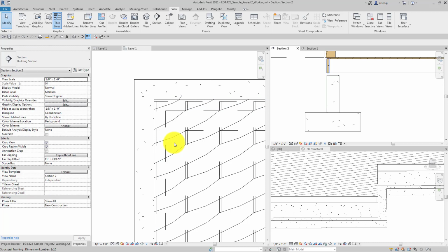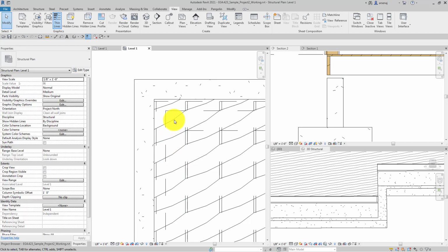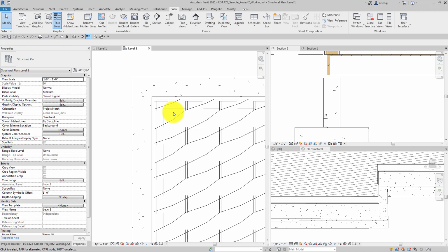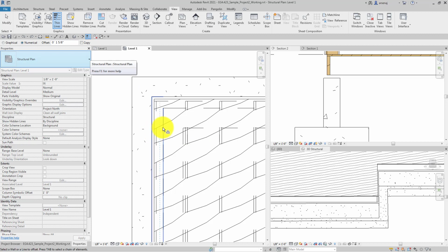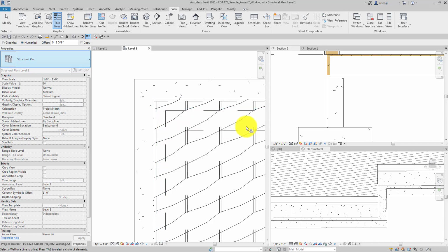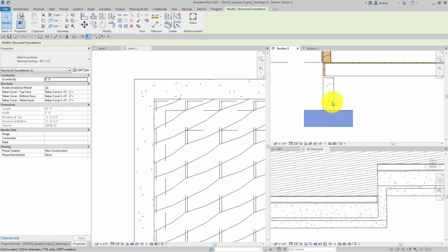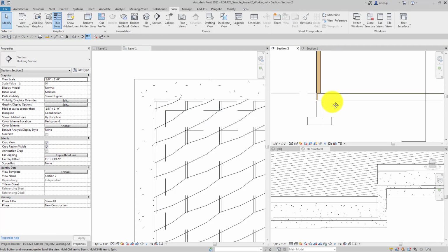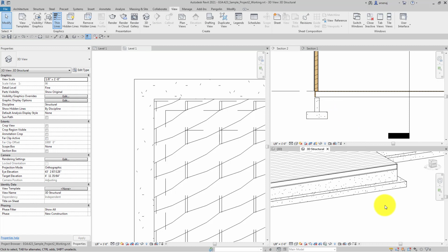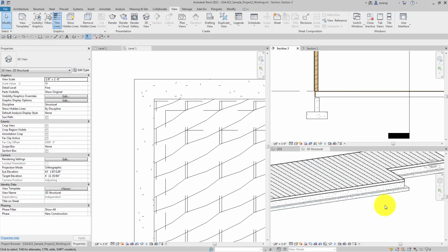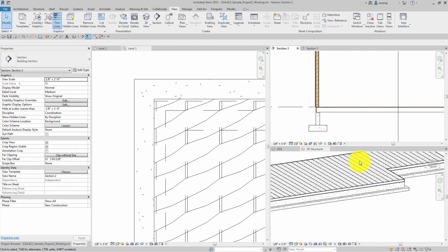And you can see it lined this edge up. So I'll undo that just because there was a little confusion there. So we'll offset at the 1 5/8, make sure copy is unchecked. Go to the inside of the foundation wall, hit tab once, see that it's all offset to the correct location and that you have the chain of walls, and then pick. And you can see that because this footing is attached to this wall, everything moved together, which in Revit makes it really nice to be able to modify things because you have that control.